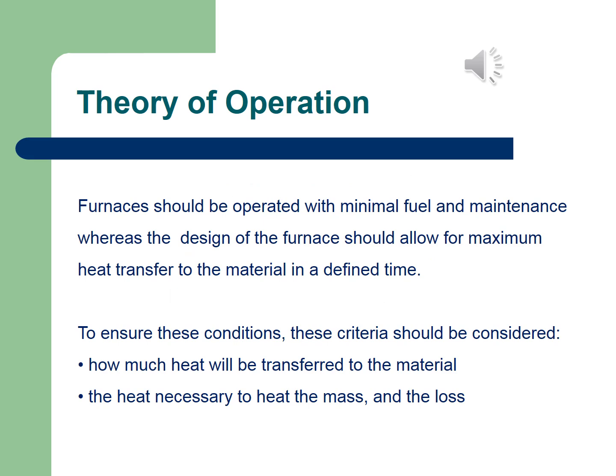I think something that's very important here is that furnaces should be operated with minimal fuel and maintenance, of course, whereas the design of the furnace should allow for maximum heat transfer to the material in a defined time. So that's the efficiency, and the efficiency of this furnace is very important. To ensure these conditions, these criteria should be considered: how much heat will be transferred to the material, and the heat necessary to heat the mass and the loss.